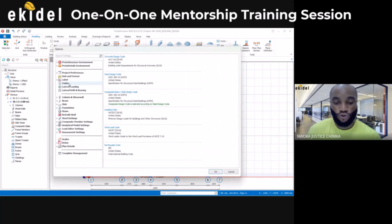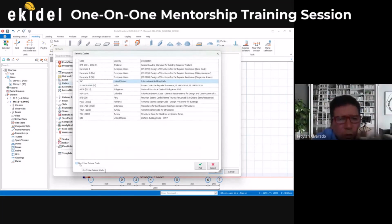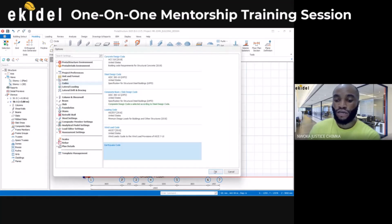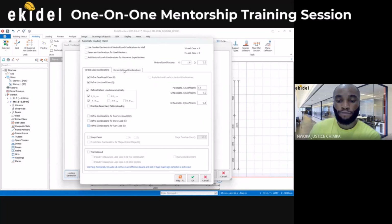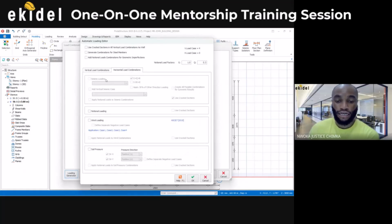I'll then come to codes. You can see codes here. I'll click on this earthquake code and say don't use seismic code. I'll say okay. If I come back to my loading, the same place we were before, you can see that seismic load is no longer added.